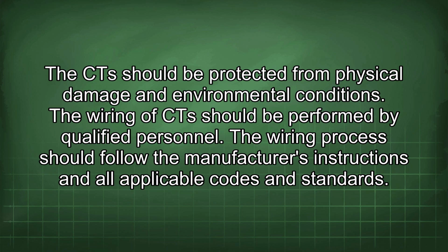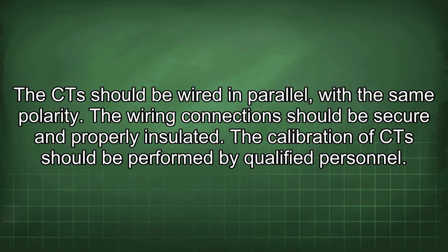The wiring of CT should be performed by qualified personnel. The wiring process should follow the manufacturer's instructions and all applicable codes and standards. The CT should be wired in parallel with the same polarity. The wiring connections should be secure and properly insulated.